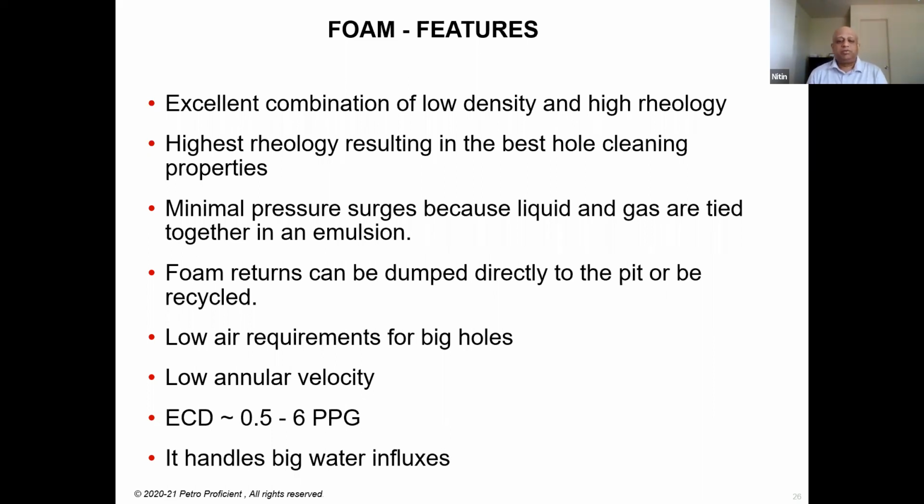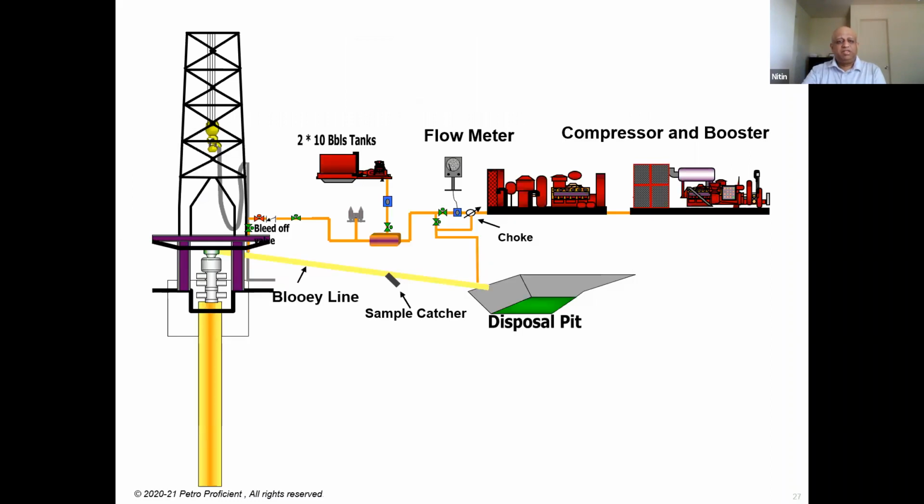And foam drilling can also handle big water influxes. So if you get water influx while you are drilling, foam has excellent hole cleaning capacity. So these water influxes can be handled very well. So this is a typical setup for foam drilling. Now here you see an additional tank and a pump that you need to include in your setup to add the foam.